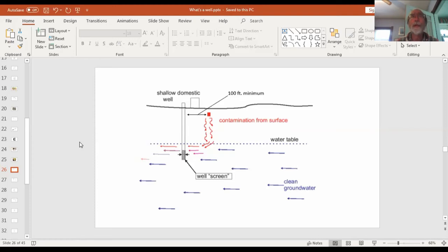Most of the things we're thinking about in terms of conventional land use would be septic effluent, which is just going to be dissolved in the water and has the same density as water, or petroleum products, which typically float. There are some hydrocarbons that sink, but gasoline, diesel, antifreeze, most of those kinds of things are less dense than water, so will tend to float. But yes, there are organic materials, liquids, industrial solvents that sink.